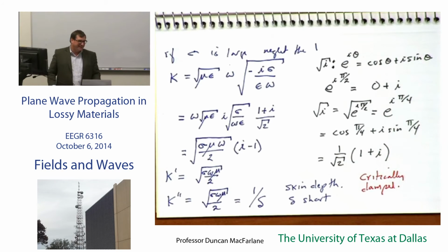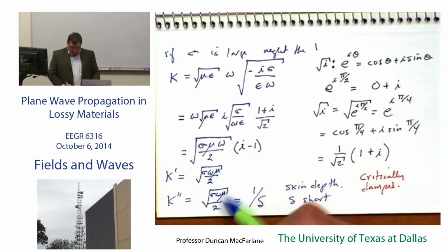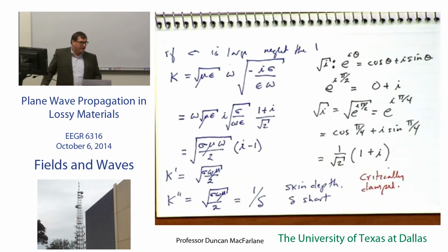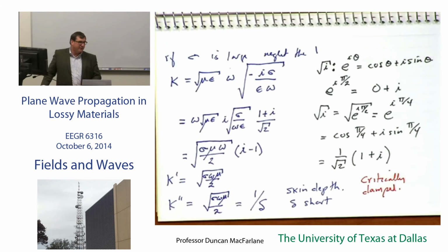Practical stuff, right? There's no dielectrics here, so it's just a metal. So there's mu, if it's a non-magnetic metal, that's just mu naught. If it's iron or something like that, you've got to figure out what you're going to do with that mu. Okay, and then you've got your frequency. You said mid megahertz. Is that like 100 meg? No, below that. So that's a small number. Yes. And that means your skin depth is going to be fairly small.